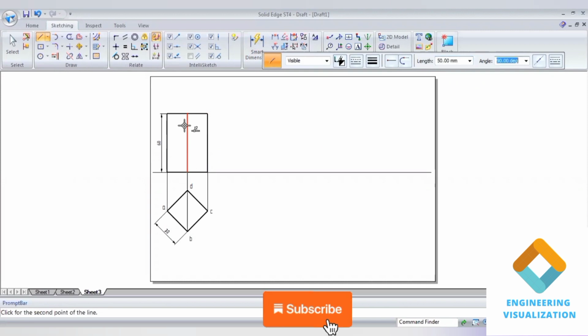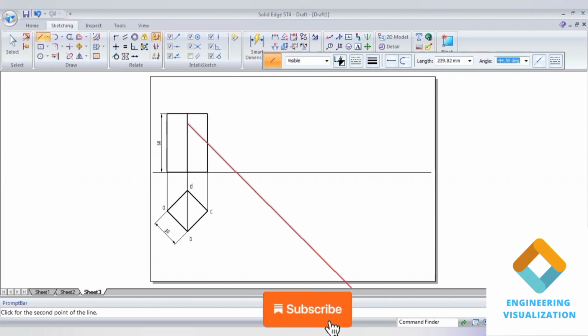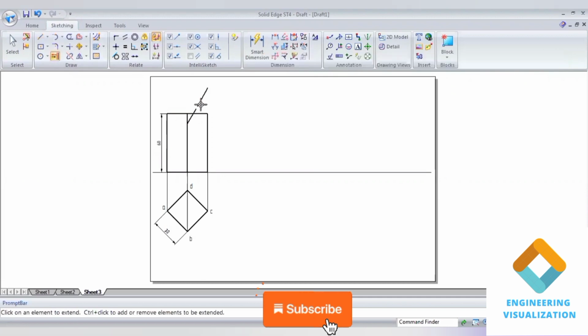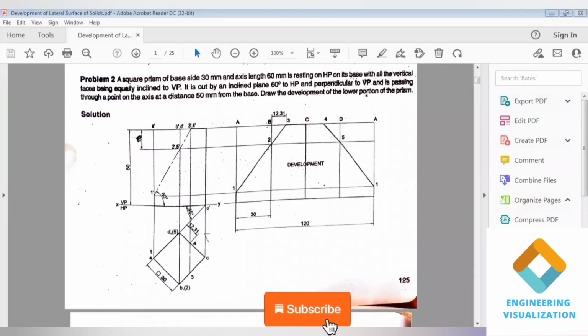60 minus 50 means 10, but I will be drawing from the bottom. So from the bottom, 50 mm length. I've drawn one line for reference, and then I'm drawing a section plane, taking this as the axis plane, now giving the angle 60 degree. That angle of inclination will be 60 degree here. So type 60 and enter. After this go to next and extend this line. This is where it is cut.